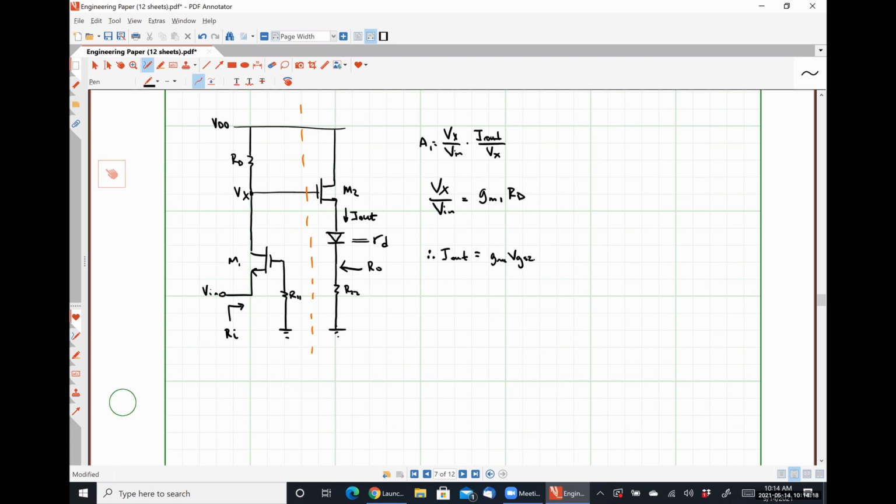Okay? So this is our starting point for figuring out what our output current is, and now we need to develop some relationships to relate probably VGS2 to the quantity Vx. Okay. So I would say that this is GM2 times Vx, which is the voltage at the gate terminal with respect to ground, right? Minus, now we need to figure out what the voltage at the source terminal is with respect to ground.